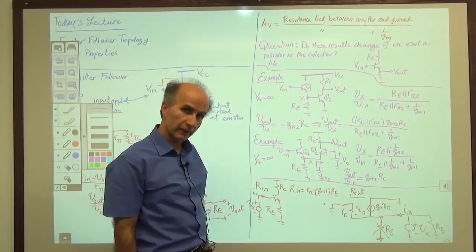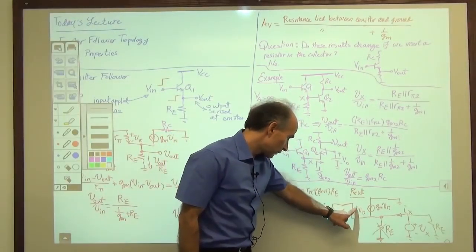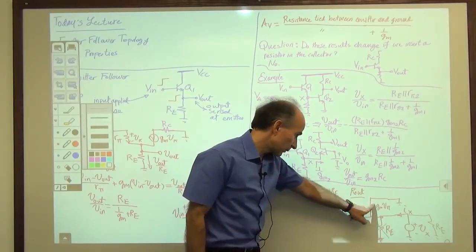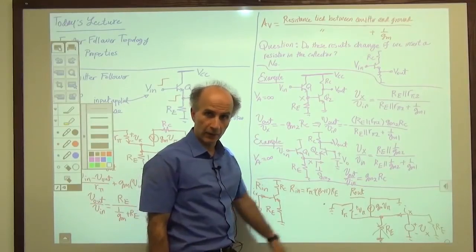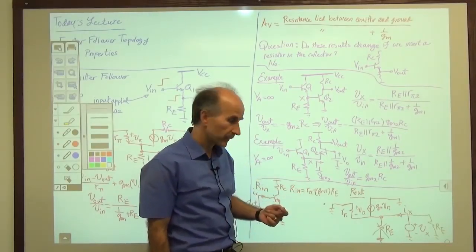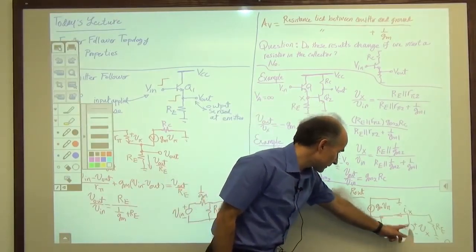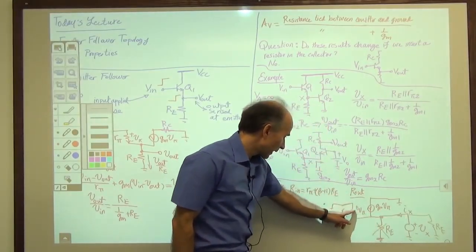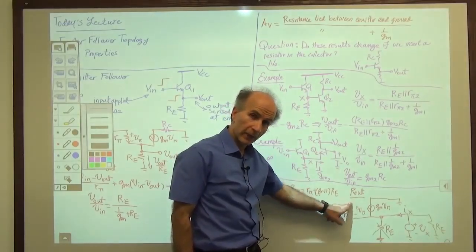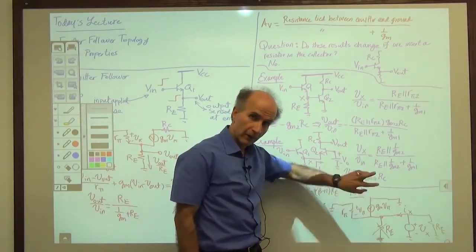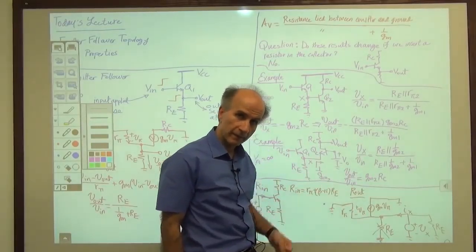Okay, how much is that? Well, we just write the KCL. We have V pi over R pi plus gm V pi is equal to minus Ix, or the three add up to 0. And we also notice that Vx and V pi are related. They're both in parallel with R pi, except that V pi is flipped, so V pi is equal to minus Vx.